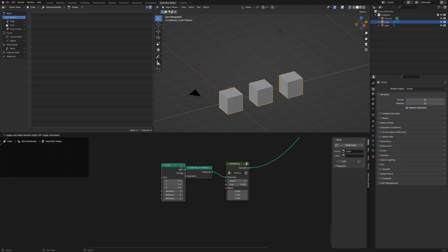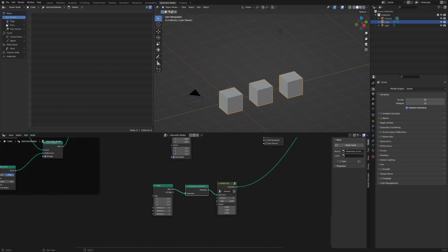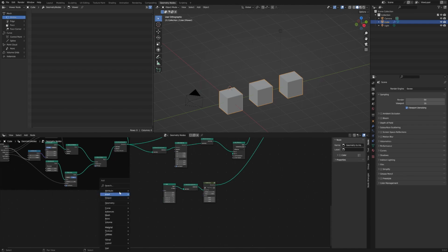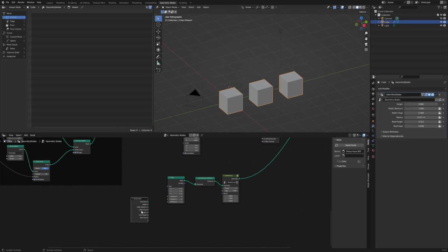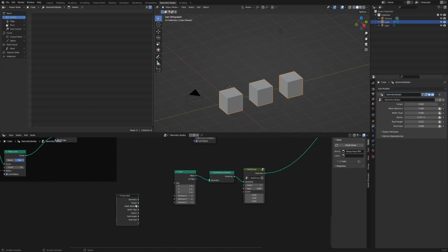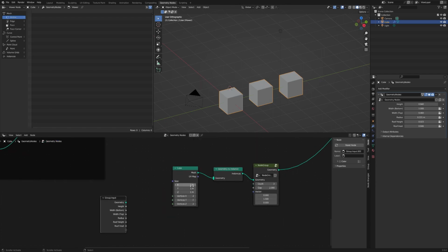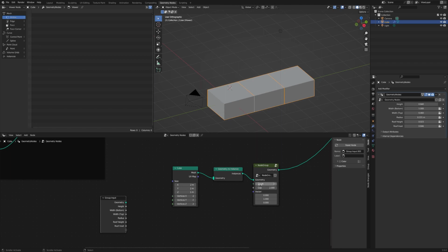So here now we can start modifying the shape of this cube such that we can get some steps, and the way we're going to do that is we're going to use our group input, because this is going to be something we want driven by that right hand side, or the actual geometry nodes over on this side, and we're going to have a thing that defines our size. Now, our size, x and y, doesn't really matter. It just has to be bigger than our base shape, because we're using these as booleans. They just have to be fairly big.